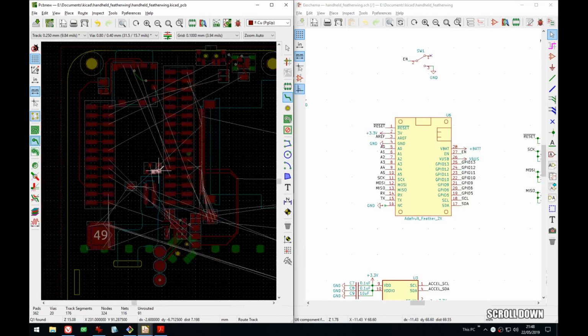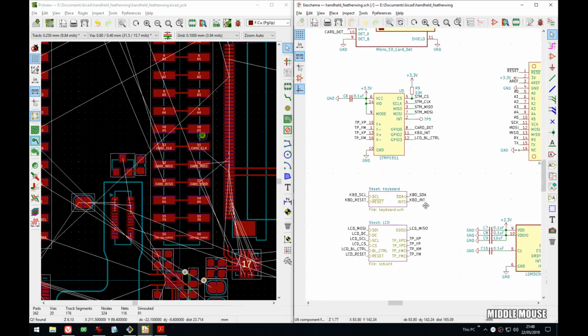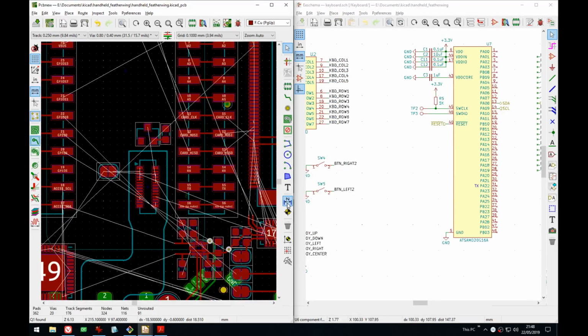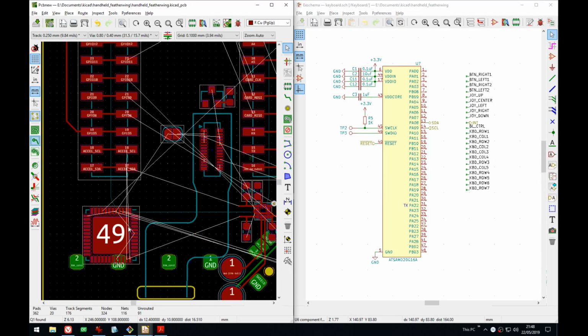Where does this go? That goes nowhere? Wait, what? Oh yeah, wait. It goes into the SAMD. Well, it doesn't go right now, but I will. Yeah, because you use I2C also to control the backlight. So it's the SAMD doing the PWM, and you just change the intensity. So you offload the PWM to the SAMD, so you don't have to worry about it. Yes, that's how it works.